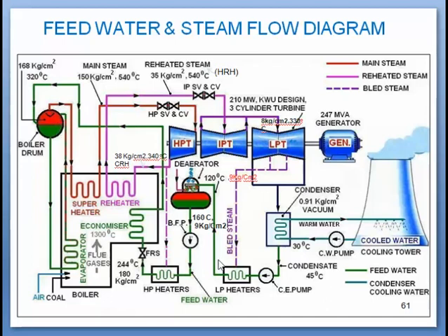So the first point, that is regeneration, is taking place in these heaters where the feed water is only sensibly heated so that its mean temperature of heat addition can be increased, which leads to the increased cycle efficiency that we had already discussed.